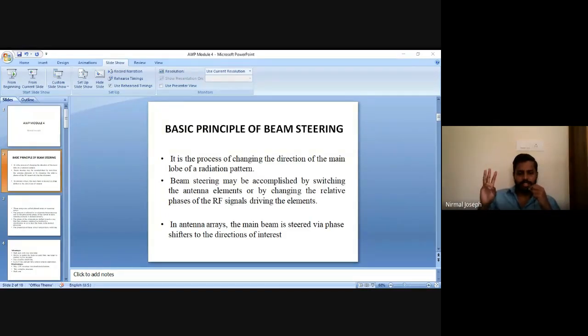Three RC networks we are using. Each will give a phase shift of 60 degree. I think you have studied this in your 3rd and 4th semesters. So in that, just use an RC network. One resistor and capacitor is enough to impart phase difference.